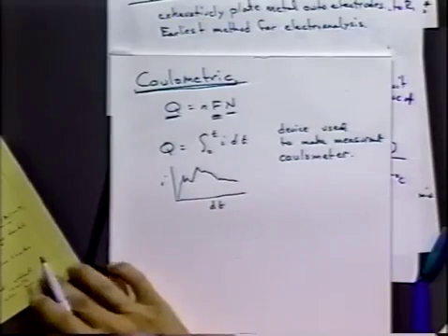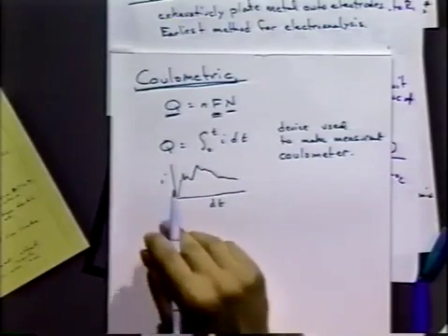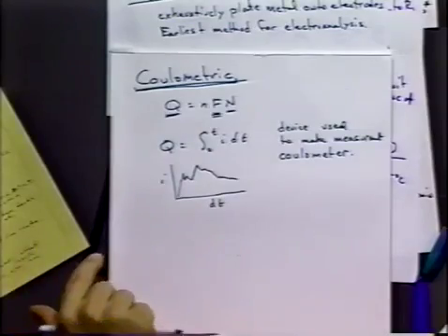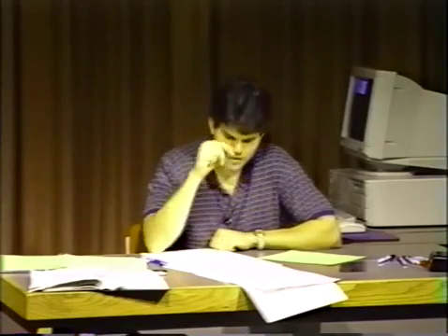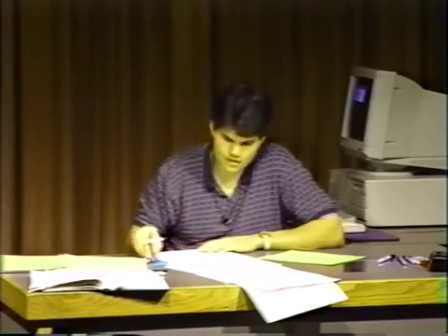The way a coulometer works is often it uses a capacitor, and it takes the current that flows in and uses the capacitor as an integrating element. So the more the voltage increases on a capacitor, the more charge is on that capacitor. So by detecting the voltage across the capacitor, you get a direct readout of the amount of charge that has been passed. The problem with all these methods is it's very tricky to get a good time measurement, and it's also tricky to get a good charge measurement because the charge cannot leak off or on that capacitor from other methods. And so for small amounts of current, that often is really, really tricky. And actually for large currents, it becomes tricky as well.